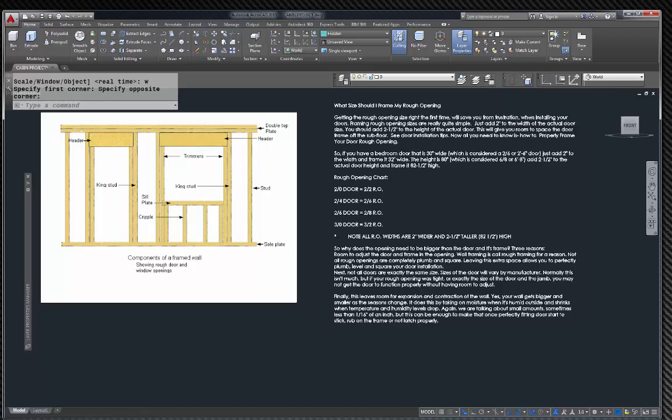But if you look at the door opening, it's actually bigger than the door itself. The door itself, a 3.0 door, means it's 3 feet wide, so it's 36 inches. And the standard is 80 inches tall, so 36 by 80. But the actual opening is bigger than that because we have to put a door jamb around it, and we have to put a door sill below it.